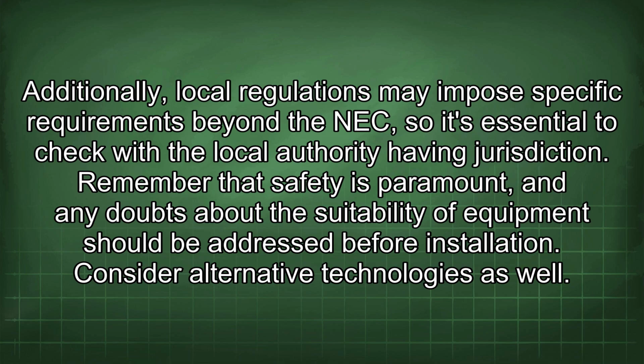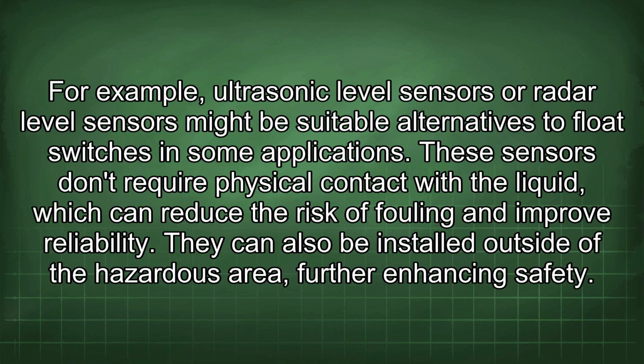Consider alternative technologies as well. For example, ultrasonic level sensors or radar level sensors might be suitable alternatives to float switches in some applications. These sensors don't require physical contact with the liquid, which can reduce the risk of fouling and improve reliability. They can also be installed outside of the hazardous area, further enhancing safety.